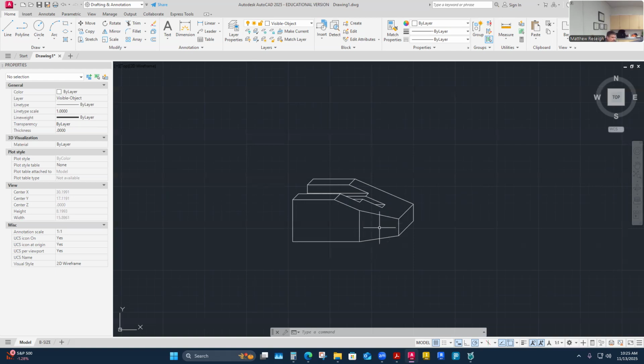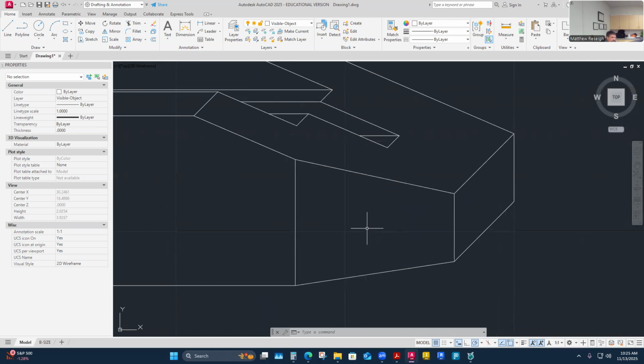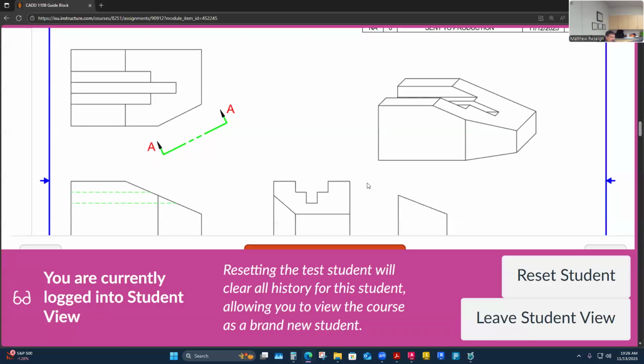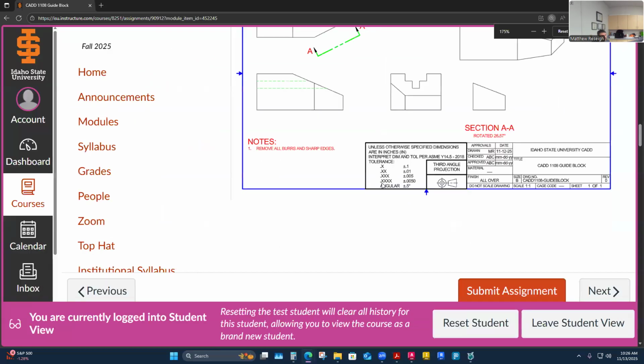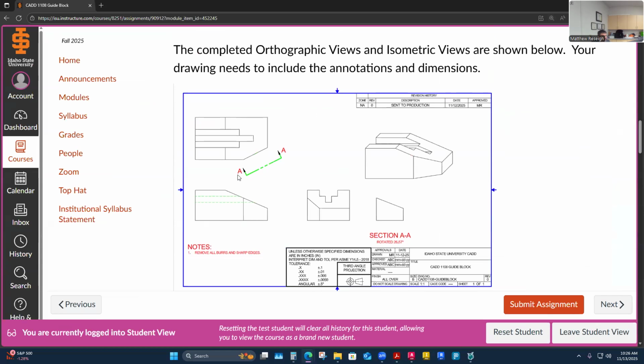And you'll notice that this will be a foreshortened surface in any of your views. Your top view will show it top down, so it needs an auxiliary view. That's why on my assignment I pulled an auxiliary view and rotated it like we did in the other one. I created a viewing plane, pulled that view, and titled it. Once you pull that view, it's going to be at this angle, and I just tipped it down so that I can dimension this essentially. The only thing I wasn't really able to dimension is maybe just this length, or this, which might be more of a width actually, just because it's foreshortened here, so I can't dimension that here.